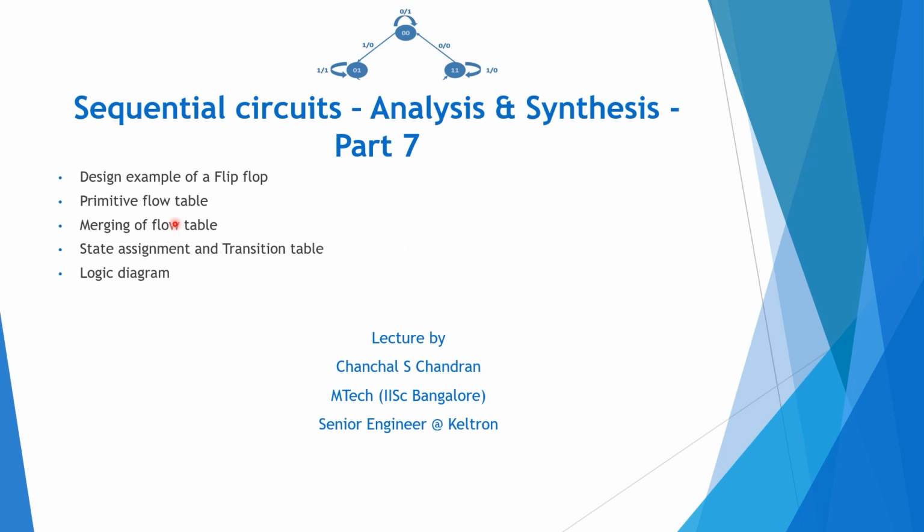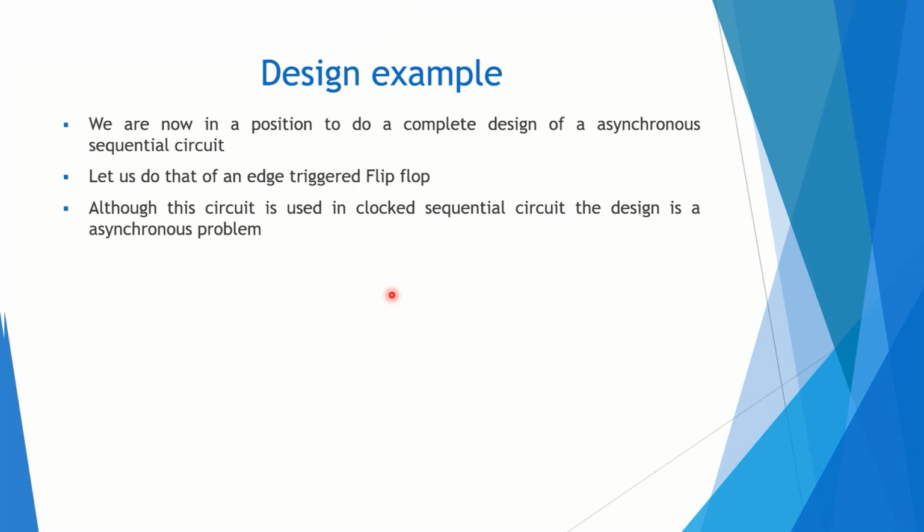These are the steps followed for the design of the edge-triggered flip-flop: primitive flow table, merging of flow table, state assignment and transition table, and then finally the logic diagram or the digital circuit for the flip-flop. So this is an introduction for the design example.